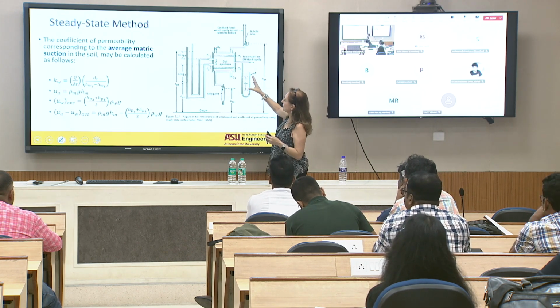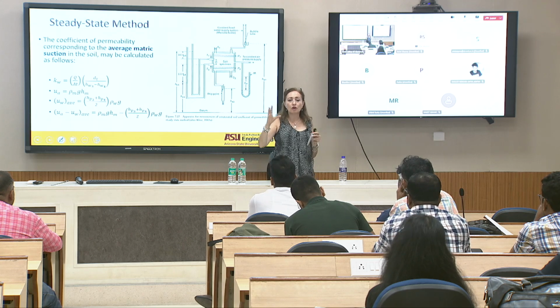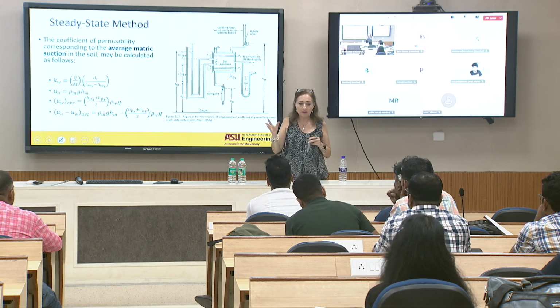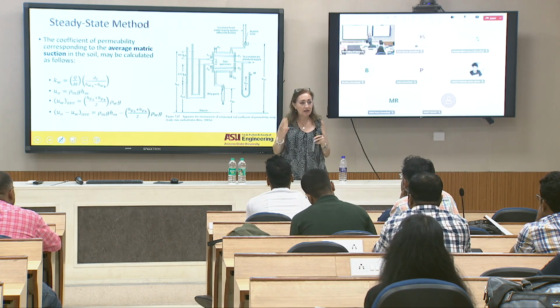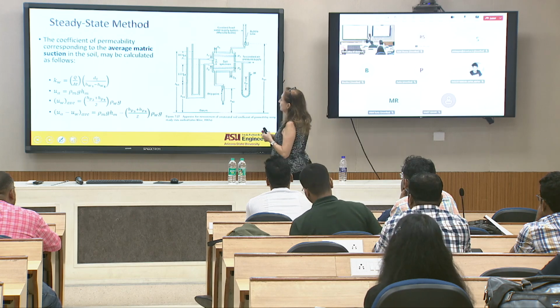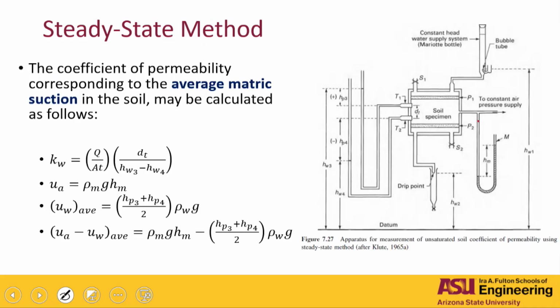And then you're going to put it at a particular suction value or water content, okay? Let's say you're going to control the suction, because you do have the time, you have the apparatus. So basically, to do that, you're going to need to put high air entry stones at the top and at the bottom of your sample, all right? I'm very sure you saw them yesterday in the lab, okay?